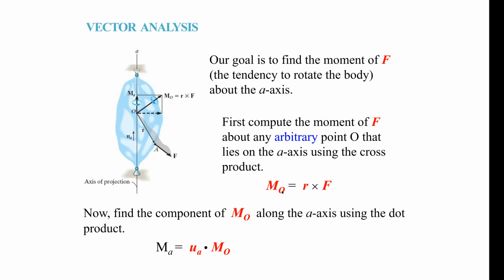In this case, like we said, we know O, so we know the moment about the origin. You dot those two together, and the end result is the projection of this moment, M_O, that we found originally, along this axis. How much of it is projected along this axis. Okay? And you could do this in general, right, for any vector.